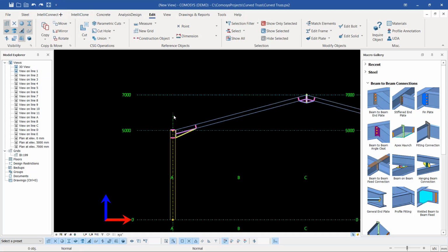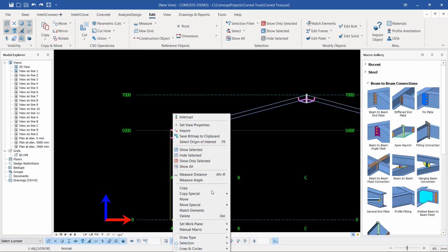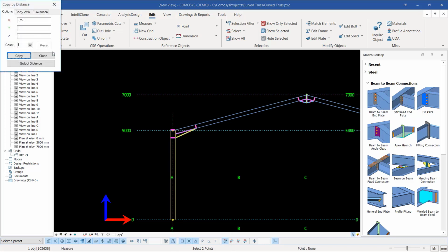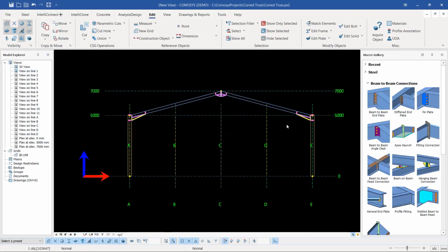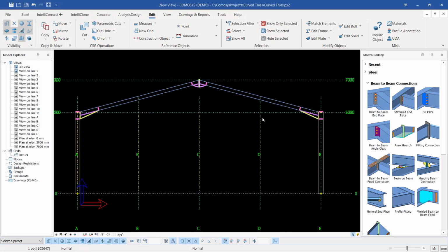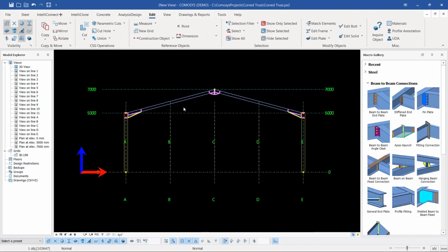I'll click undo, then select on that, right click and come to spatial copy once again and click linear. So this time around I'll add them to before and click OK, then close that. So we have this in place. But if you take a look, our grid line is slightly shorter, because with reference to the apex, it's way off.